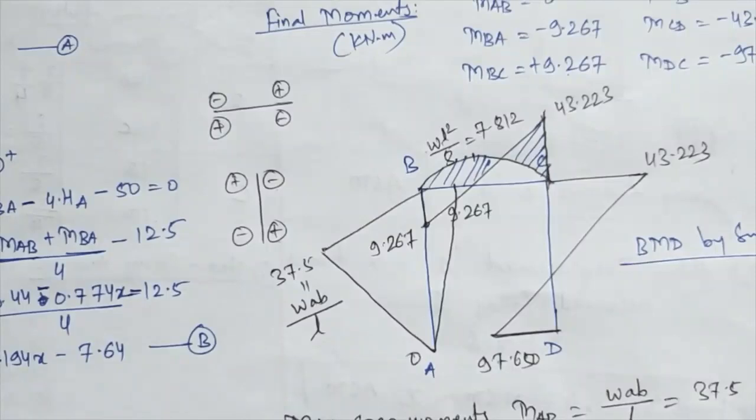Okay, so this will be your numerical of sway frame by using moment distribution method. The numerical is actually lengthy because here mostly two steps are increased. Your sway analysis is increased two times. You have to carry out the moment distribution table, and your shear equilibrium equation is also increased. That is why the length of numerical is much longer.